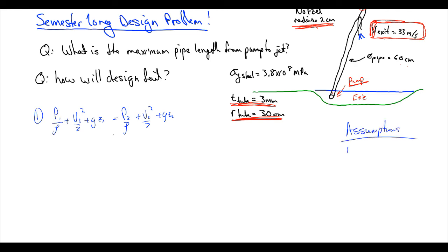One, we're going to have to assume inviscid flow. And remember, we're writing this down so that our future coworkers know we had to assume inviscid flow, and that's a terrible assumption. But we have to, because right now the only tool we have to tackle this problem is Bernoulli's. So we have inviscid flow, density is equal to a constant. That's a pretty good assumption, right? And we assume that it's also steady. Steady is not a bad assumption. We're doing the same things over and over again.